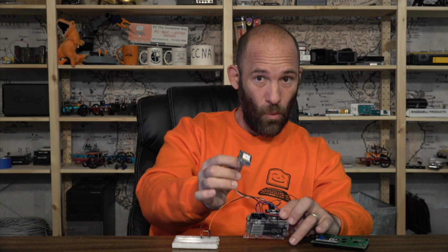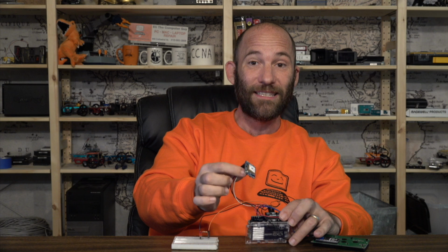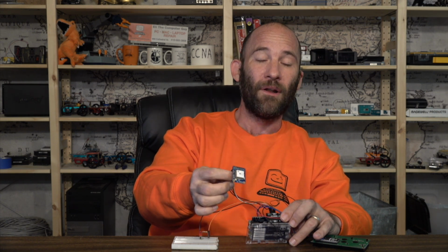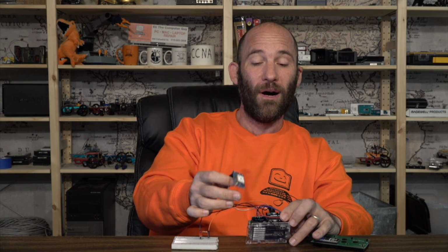So again, we're going to be using the Adafruit Ultimate GPS. We've used this in a couple of previous classes. With this GPS, what I have found is that for some reason, it seems to work best when I'm using an Arduino Uno with Wi-Fi. For many projects, I use Arduino Unos, but when I use an Arduino Uno with the Adafruit Ultimate GPS, the latitude is way off. It's always putting me down in North Carolina. Don't ask me why, but as soon as I start using the Arduino Uno with Wi-Fi, those coordinate problems clear themselves up. So that's why we're using the Arduino Uno with Wi-Fi.